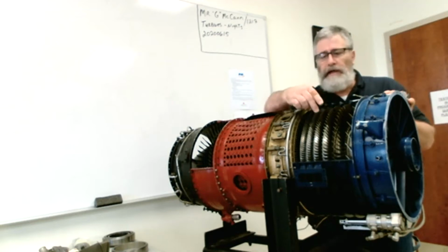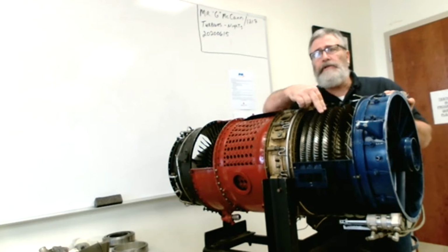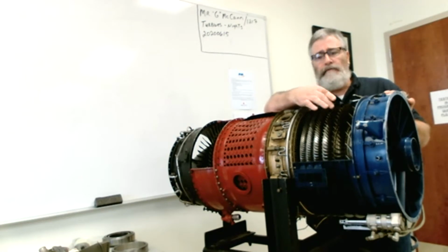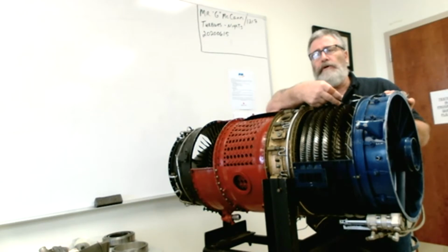Okay? Now, one more thing on these axial blades. I'm just going to throw this in, seeing as I'm making the video. We have a type of compressor blade that is referred to as a profile blade. That is the name of it. A profile blade has a very thin tip, the outer tip. The tip clearances between the case and the compressor blade are very small, so somebody had the good idea to make the tips extremely thin.